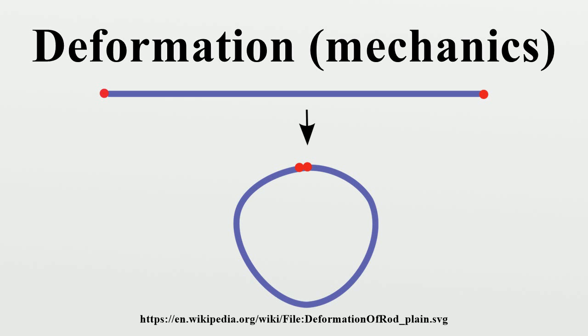Strain. A strain is a measure of deformation representing the displacement between particles in the body relative to a reference length. A general deformation of a body can be expressed in the form x = F(X), where X is the reference position of material points in the body. Such a measure does not distinguish between rigid body motions and changes in shape of the body.